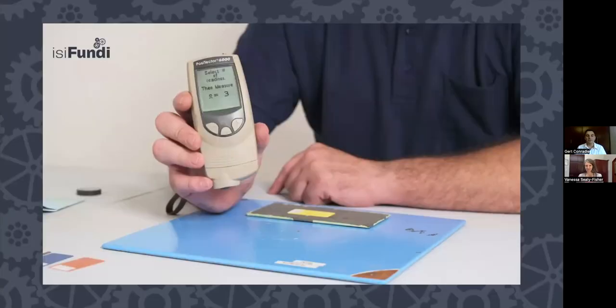And quite rightly, you mentioned two different methods of measuring. This is what's done on a rough calibration. So a rough calibration is obviously your blasted surface. And the reason for doing that is because you want to measure coating thickness over the highest peak. Otherwise, you've got peaks that are sticking out of your coating. So what the gauge does, the electronic gauge, you need to set it up with a known shim or a coating of a known value over the highest peak. And that's this yellow thing that you see here on the steel plate. That's a plastic shim. And now you will adjust your gauge according to what that known thickness is. Once you've set this gauge up, then it will now record accurately.